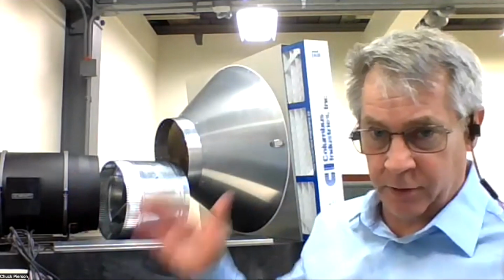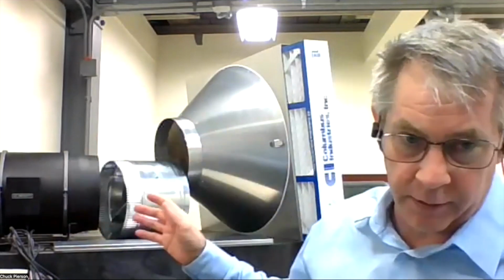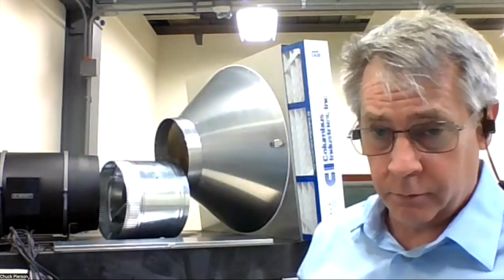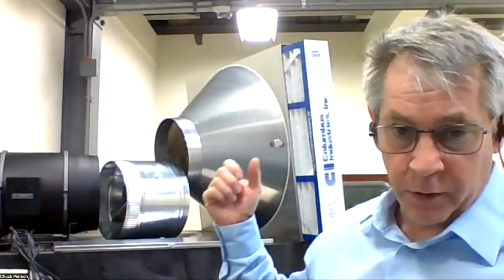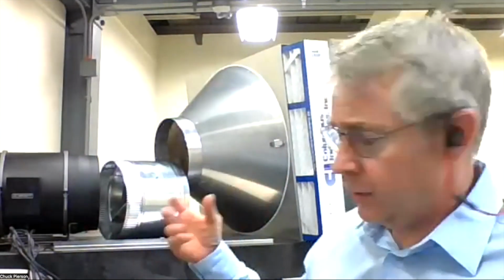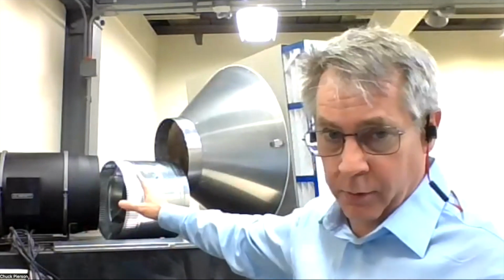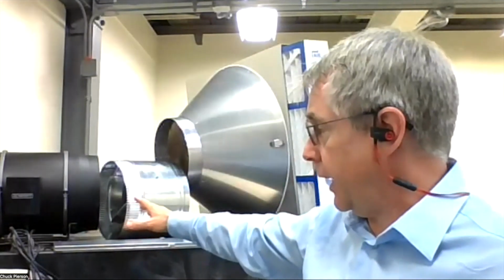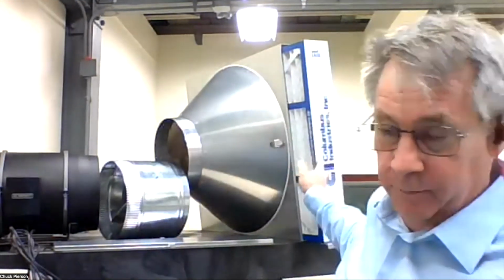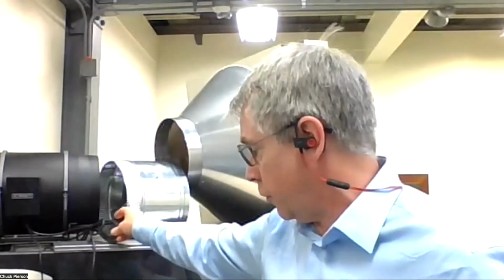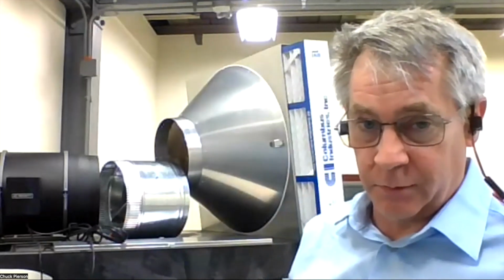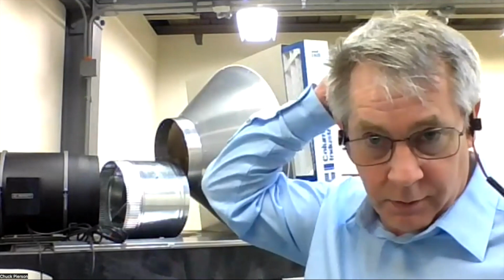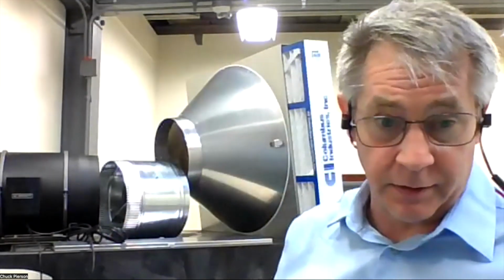The original design had a fan on each end, a fan on the inlet and a fan on the outlet. I think in version 1, we're just going to have the one fan attached on the downstream side, so it'll be a draw-through configuration. And so we'll have a damper on the inlet and a damper on the outlet, and then a fan on the outlet. And this is a really good multi-speed fan. It has a really nice controller on it that David is going to be able to program through his system, where we can modulate the speed to test it at different airflows.